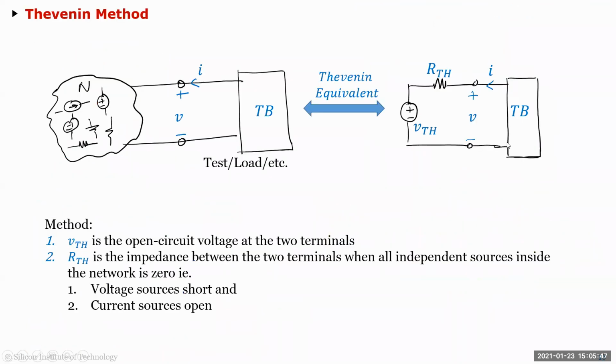Okay. All right. So the last two things I wanted to cover on the network are the Thevenin and Norton equivalents. I think everyone knows this, so I'll just go quickly. If you have an arbitrary, again, linear time invariant network, it cannot be a nonlinear network, then for that network, if you have another circuit or a test bench or a load, the best way to check that, if you can, is to make a Thevenin equivalent. The Thevenin equivalent is this circuit here, right?